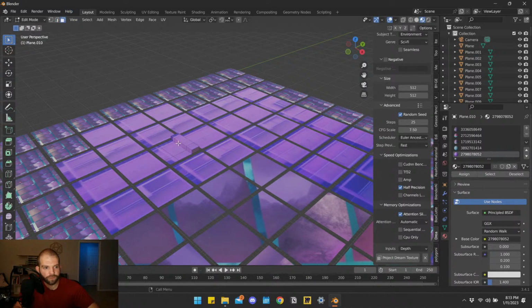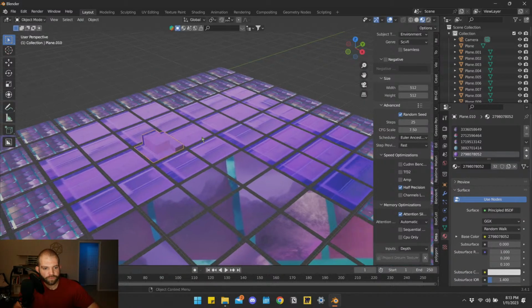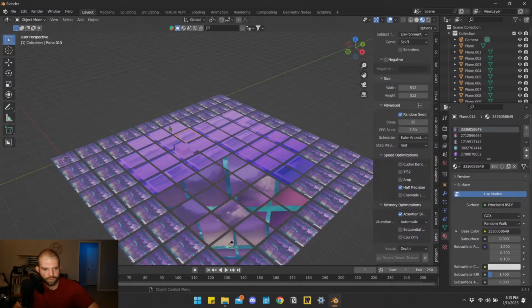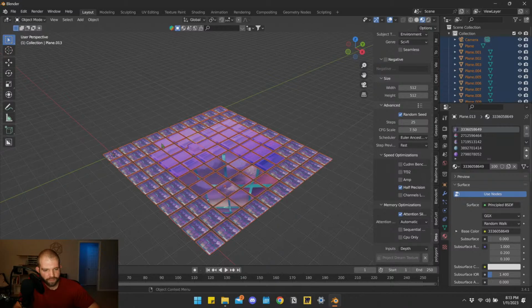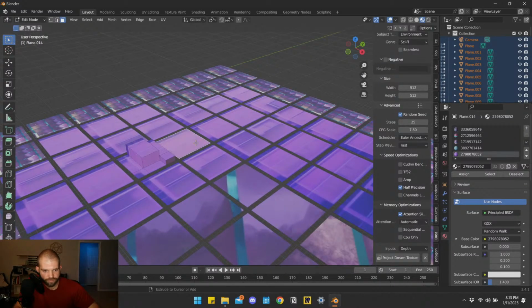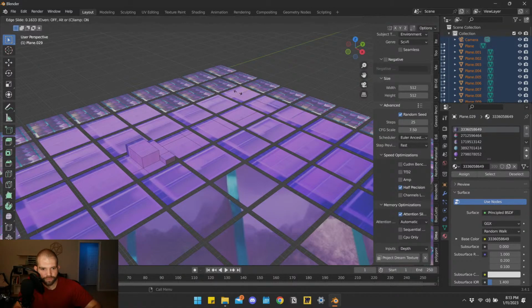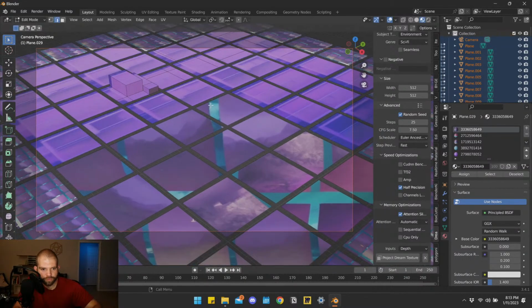So we'll use these faces to extrude. I can select all of them and they can remain their own object, but I can just edit them all together at the same time. And I'll just keep doing some loop cuts to introduce some depth into the model, and work all of this from the camera view.